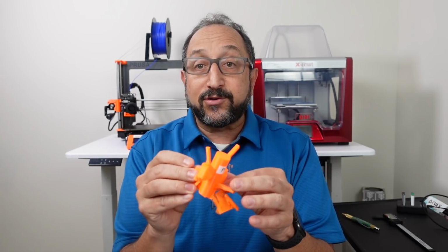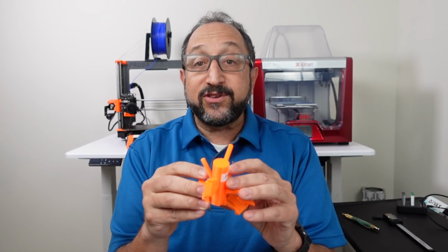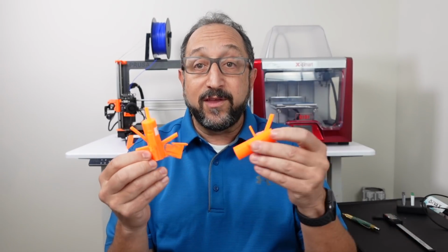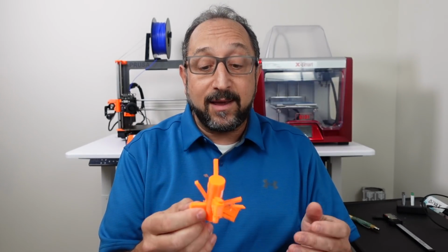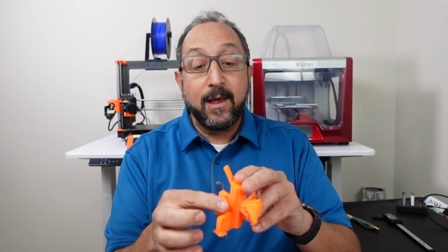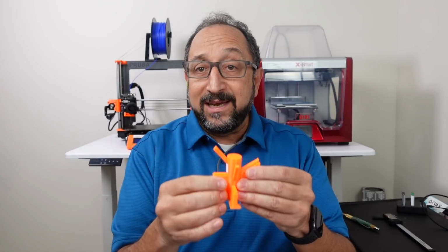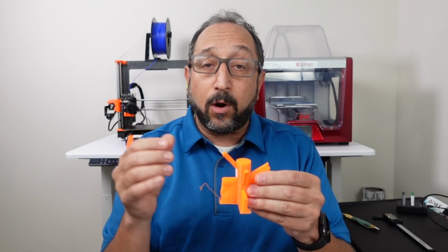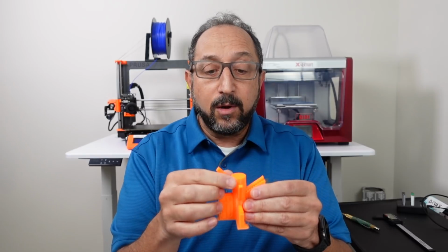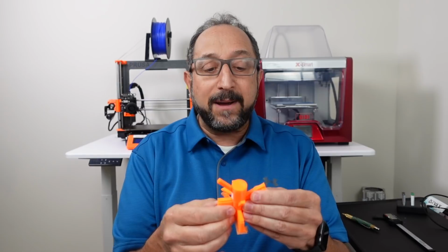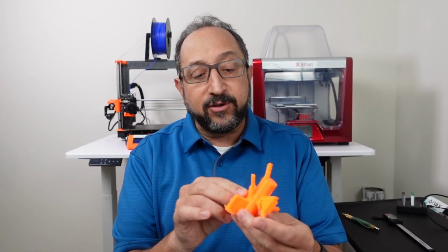by the PrusaSlicer seem to be a little tighter to the actual print and quite a bit harder to remove than the supports from the Cura Slicer. Once again, could I tune that? Absolutely. On the other hand, these overhangs that did not have supports are actually a bit cleaner on the print produced on the Quiddy with the PrusaSlicer, which means potentially flow rates and cooling might be better on this printer. Overall, these are both pretty good prints.